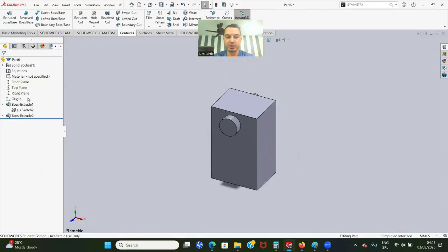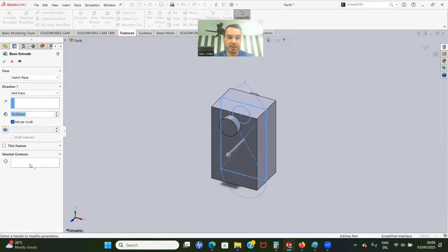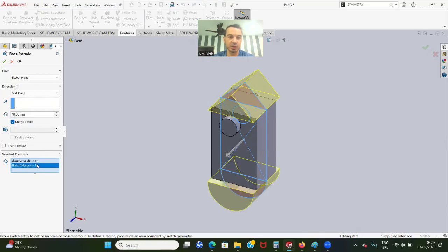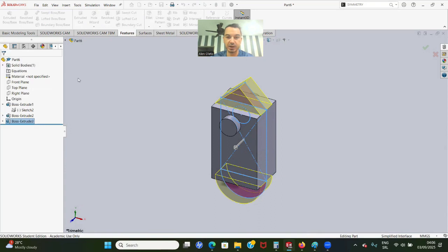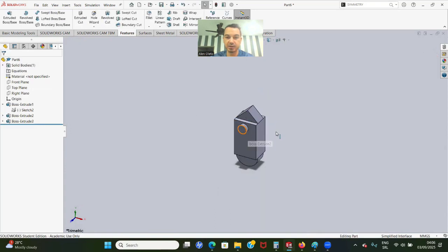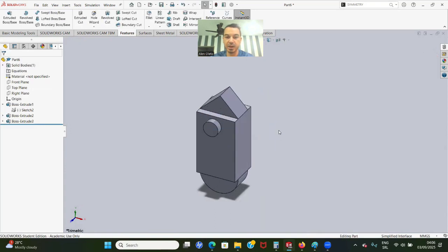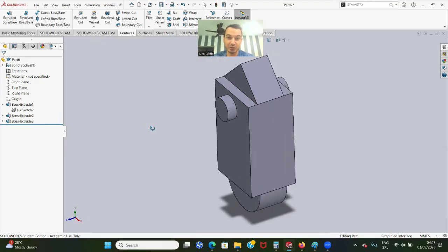Now what we did, we used the same sketch by multiple features, and we can just repeat this process, as long as we want. So we can click here, go to the Extrude Boss, select its contours, and we can select, for example, this one, we can select this one, we can combine them together or go separately. Let's say go 30 depth. Let's click OK. Like this. But also I can do this using Extrude Cut, right?